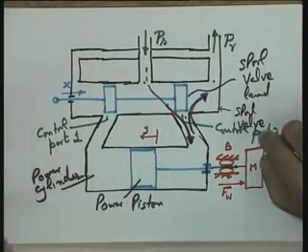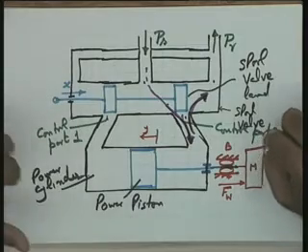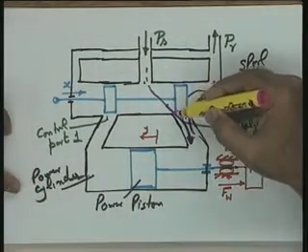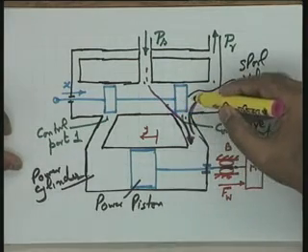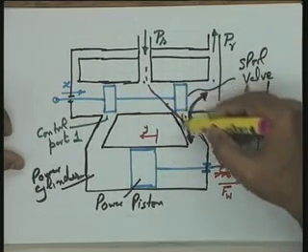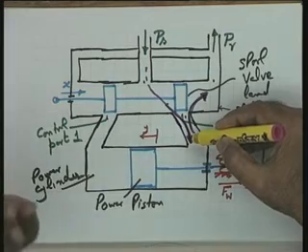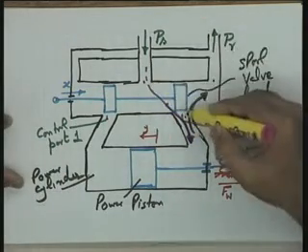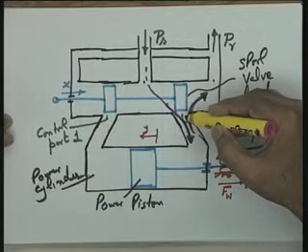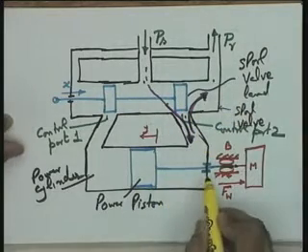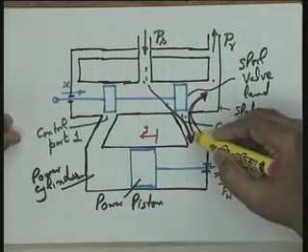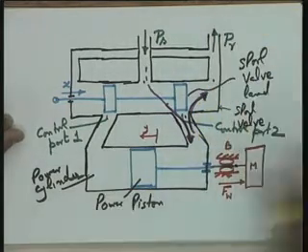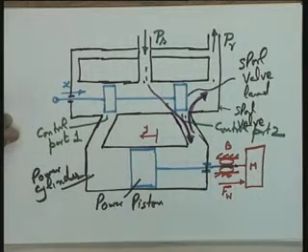Please see that this is effectively possible in this particular case, provided the leakage flow, let me use the word leakage flow because it is not the designed flow. This particular flow in the neutral position is not the flow required for power action. So, let me call it a leakage flow. If the leakage flow at this particular control port into the cylinder right hand chamber is equal to leakage flow out from the right hand chamber into the drain, the y is equal to 0 condition is realized.